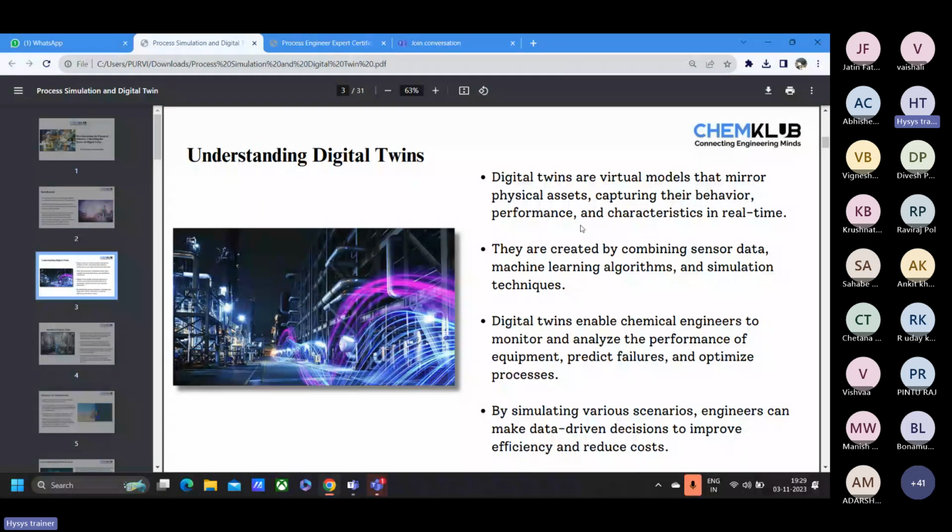It shows what the efficiency of that compressor is, based on the performance curve given by the vendor, and then you can take action, for example, that I have to reduce my density. Then you will decrease some of the components or composition, which you can try to optimize by maximizing your compressor efficiency. Then whatever performance or characteristic you get from those models, along with your digital analytics, that is statistical analytics,